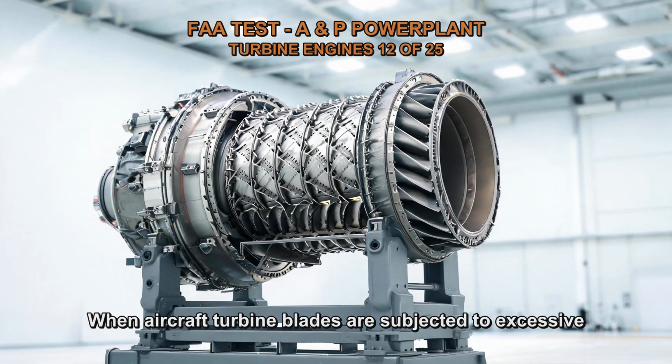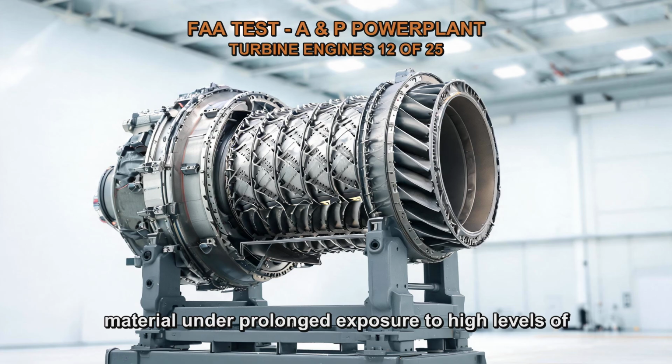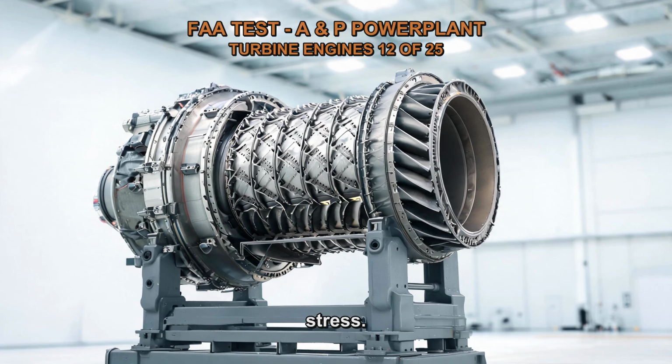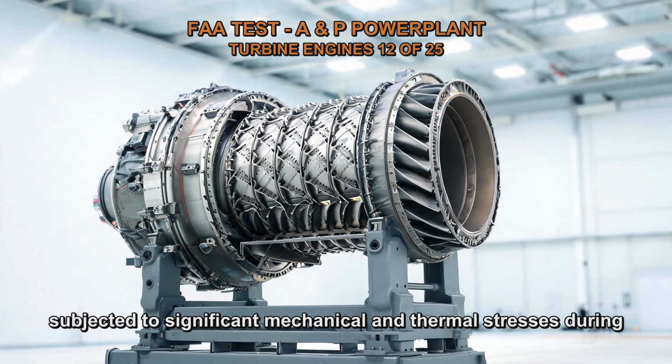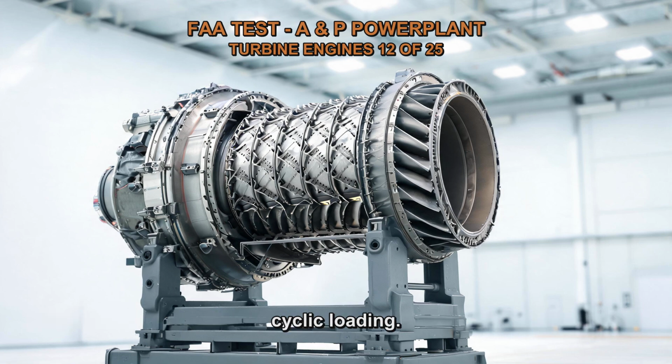When aircraft turbine blades are subjected to excessive heat stress, stress rupture is the type of failure that can be expected. Stress rupture refers to the failure of a material under prolonged exposure to high levels of stress. In the case of turbine blades, they are subjected to significant mechanical and thermal stresses during engine operation. These stresses include centrifugal forces, high temperatures, and cyclic loading.